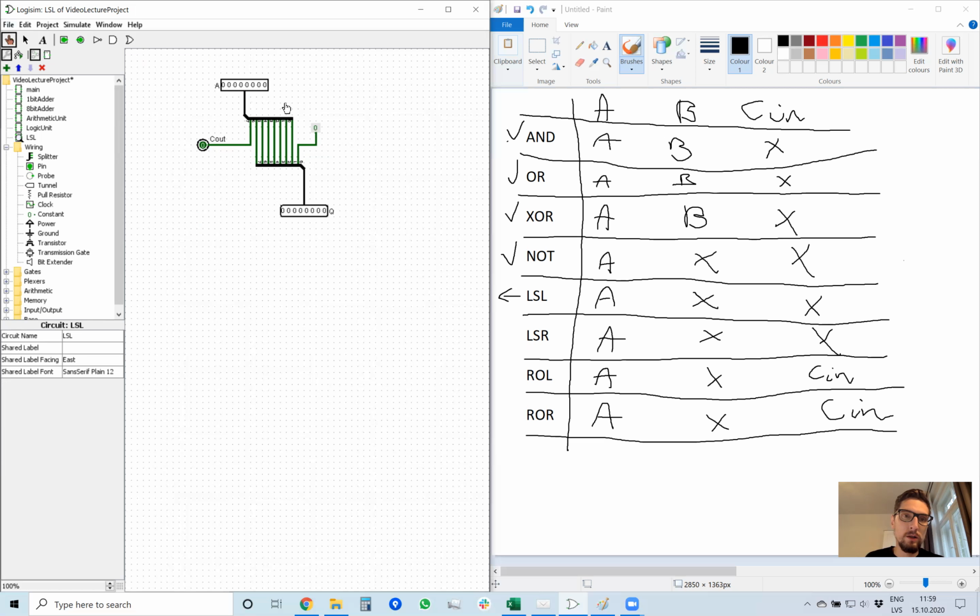So let's check it out. Let's say, for example, I have input 1, 1, 0, 0, 1, 0, 0, 1, like this. So all bits are shifted left. As we can see, 0 is shifted into the 0 position. So 0, 1, 1, 0, 0, 1, 0, 0. And the top bit is pushed out to carry out. So this is the first place where we are using this carry bit, but instead of pushing it in, we will store it in the status register.